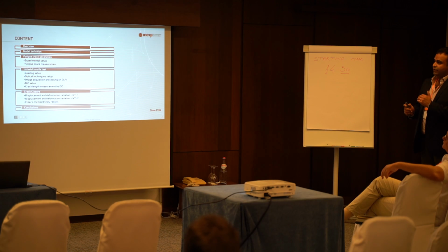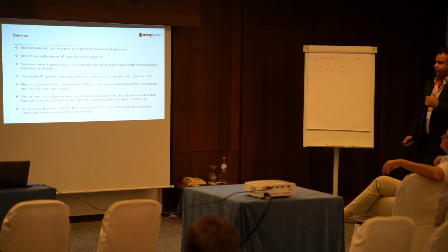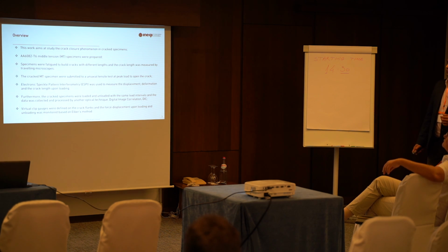At the end of the process, it was possible to say something about the crack closure based on the displacement and deformation field, and also by the Elber method, which is very famous in crack closure analysis. The motivation of this work is that crack closure is a hot topic these days in aeronautics, especially in launchers and the shuttle, and also in the automotive industry, in order to prevent further fatigue crack growth in their components.